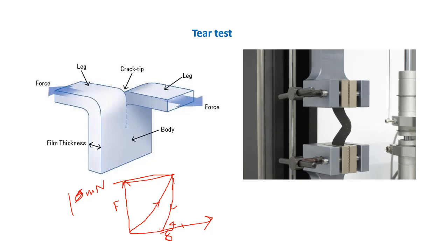So from this experiment, I am showing what is happening in the nano indentation test. I am putting an indenter on a surface, and it will give me a mark on the surface. If it is a pyramidal indenter, I get a mark like this. And the machine will calculate the hardness.